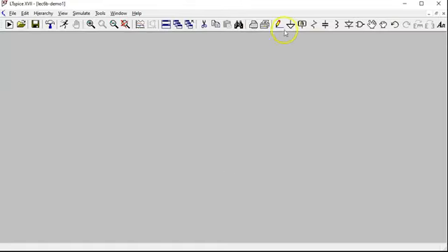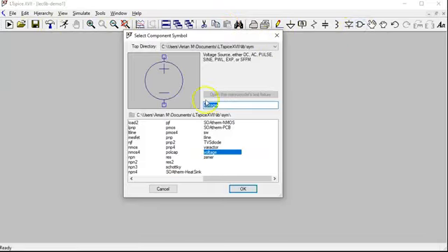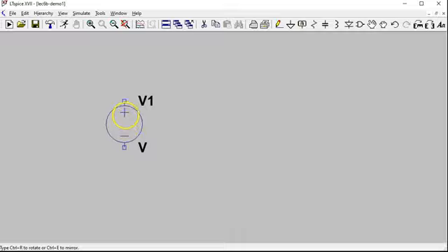Okay, so let's just go ahead and create the circuit. The way I'm going to do that is I'm going to go into the components section and look up voltage, then click on voltage here, place it, click, and press escape. Then I'm going to put down 2 resistors from this menu. I'm going to press Control R to rotate and place it in a nice manner. Then I'm going to click again, first Control R and click again.